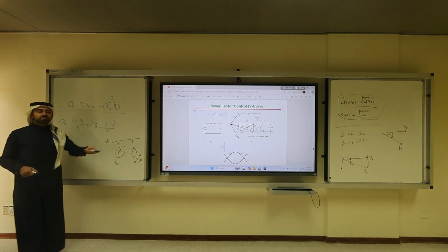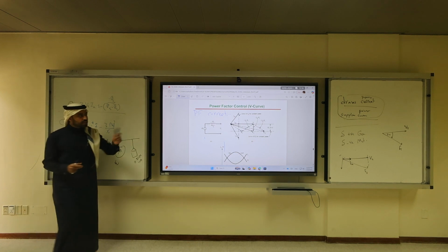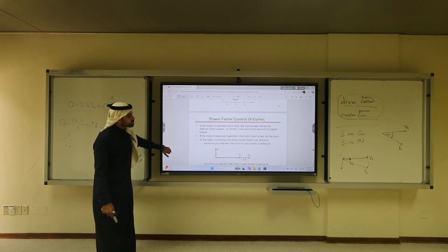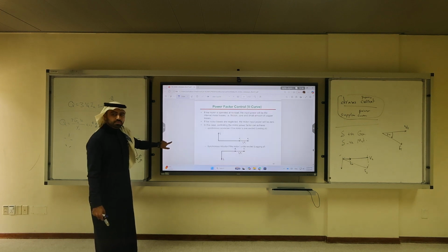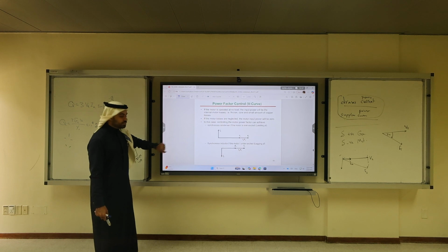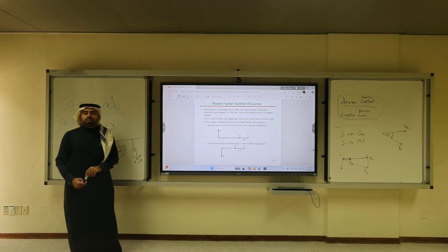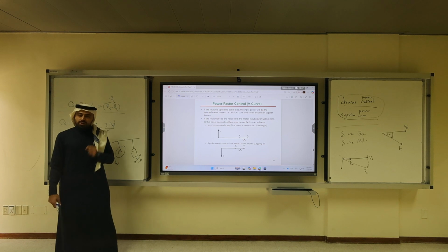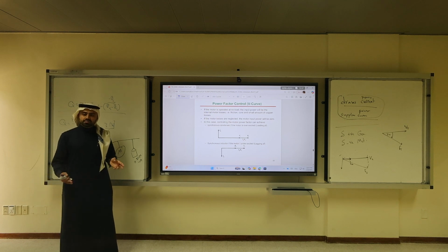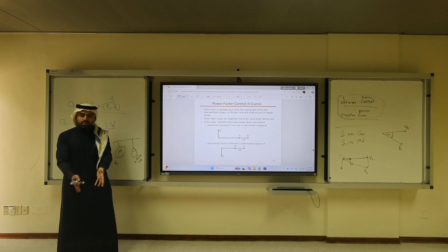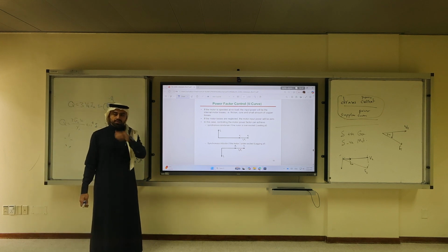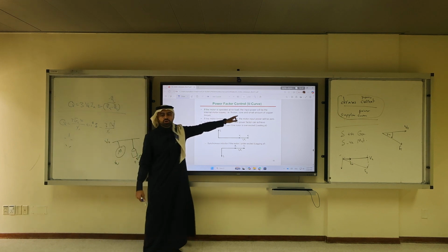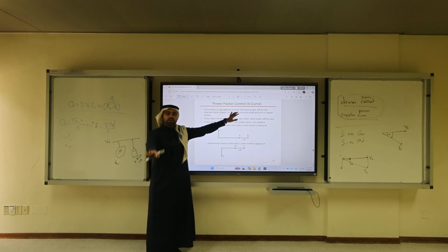I'm not using the shaft torque, and I'm going to show you now in a second. Can I use it if I want to? No, this motor is used only to fix the power factor. If you use it, you would draw more current, and depending on how much load you put on the motor, you would change IA, and that changes the whole design. This is empty, so this motor operates at no load by design.